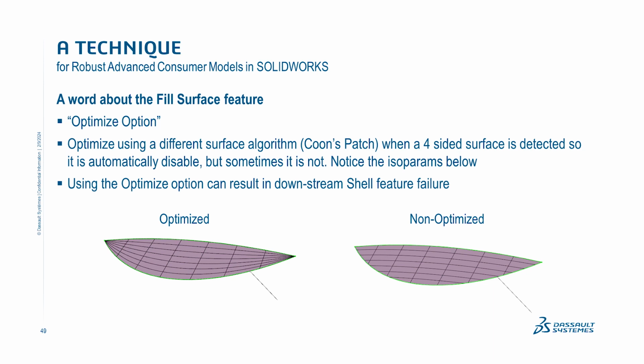But for anything that's 3 or 5, use fill. The reason is that fill is a powerful feature that derives its own isoparam direction within the patch. That's really important, as I'll show later in my presentation, because sometimes boundary even has this problem on 4 sides, where you get degenerate edges or points in your surface. We'll talk about that hopefully in a bit.